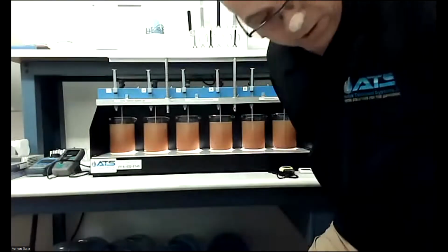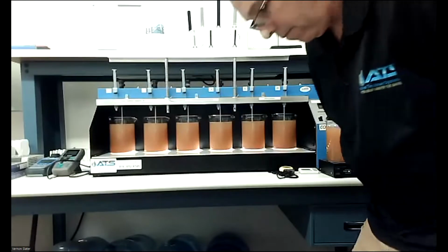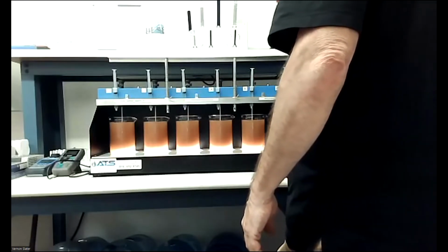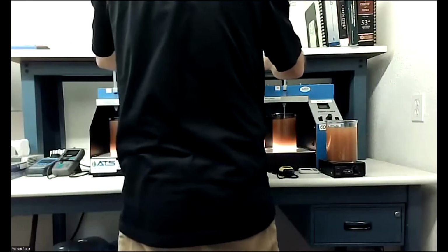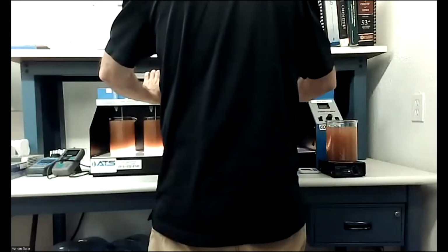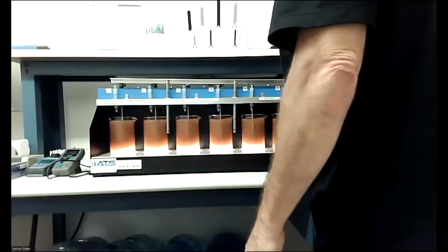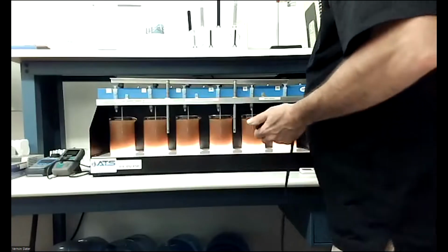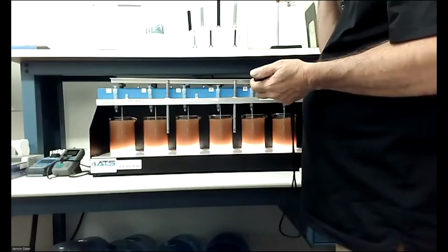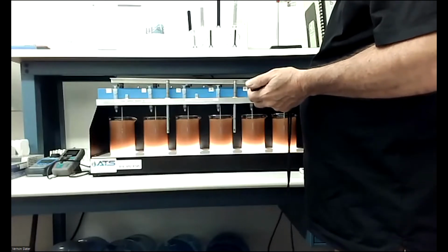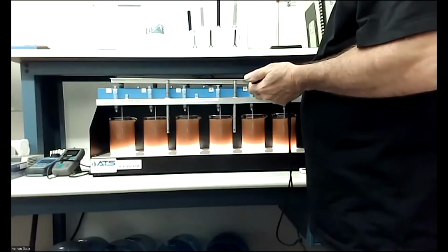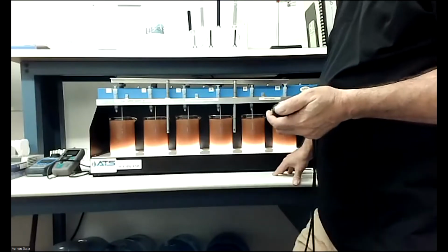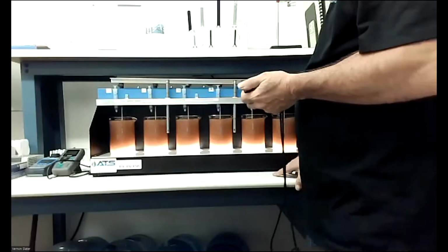So I will start this, get my chair out of the way. Okay, we're all injected. I'm going to start a stopwatch. I'm running about 1 minute on the flash mix and 30 seconds to settle. And that settling period is just a slow mix. And then after 30 seconds, I'll stop mixing altogether.